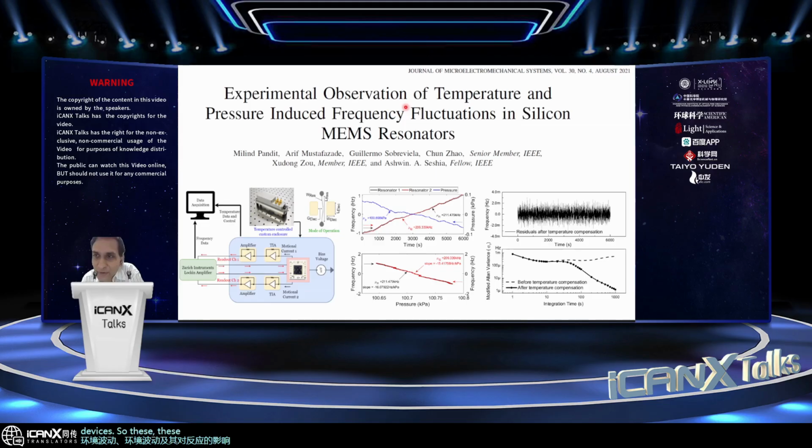So these tuning forks are incredibly sensitive. They pick up not just the measurand, but they can be coupled into temperature variations and pressure variations that need to be compensated for, potentially compensated for at multiple levels. So you can talk about compensation at the material process level, at the device design level, at the circuit level, and then even beyond the front end circuits, compensation that can be done at the package level and so forth.